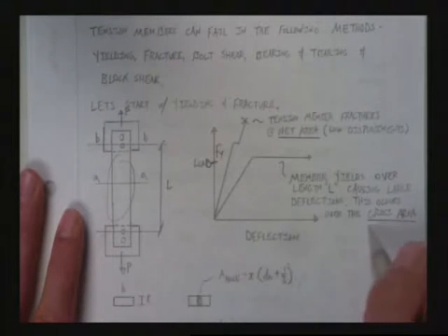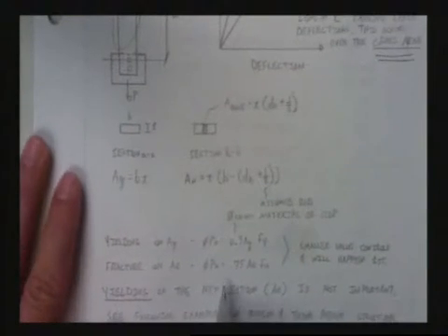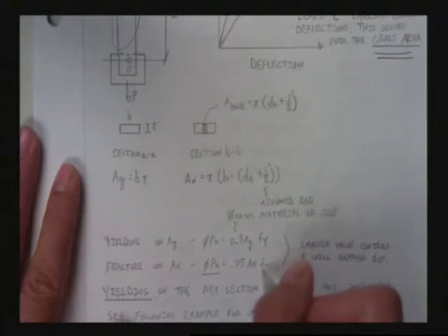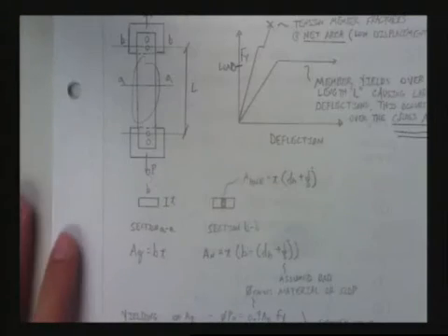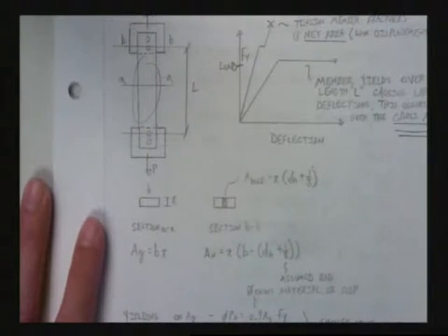This occurs over the gross area. Okay? Now, when we talk about a fracture, we talk about the equation for fracture. We say phi(PN). Again, that's the nominal capacity. It's 0.75 A sub E FU. My favorite variable in this class, FU. Right? Now, we're not using yield. Why not? It's past yielding, right? Since we're yielding in a small area, which we're going to talk about in a second, it's okay to yield, right? Yield's no big deal. We're going to allow it to go to fracture, right?